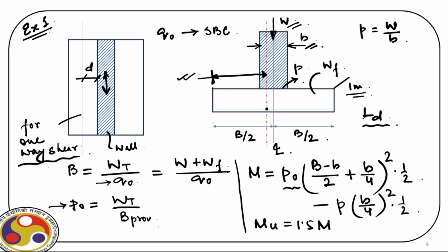You all know the expression for Ld. We will see when we take an example with some numbers. So this length should be more than the Ld. If by chance this is not, then we can actually turn it and take it to the other side. Or otherwise we can extend it and we can go this way also. In any case, we have to provide sufficient length of these bars covering the minimum requirement for this development length. That point to be noted, and with that only our design will be complete. So we have to check against bending, we have to check against shear, and then finally against the development length. And that completes the entire design procedure in steps.